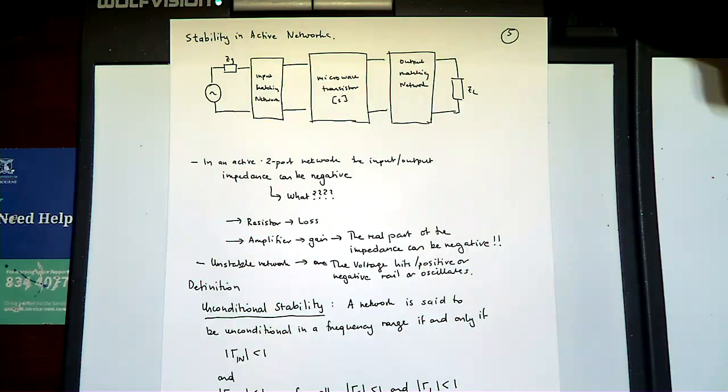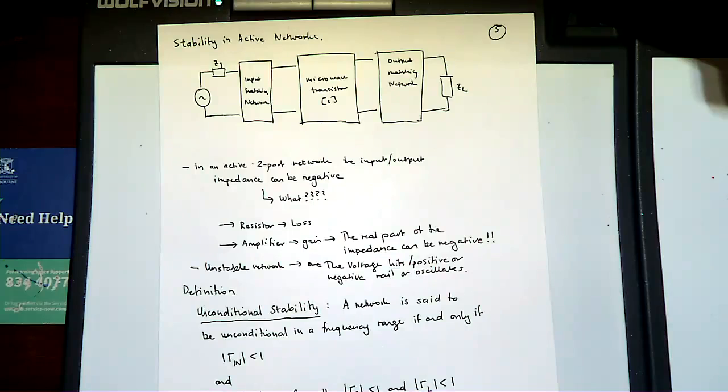That never happens in practice. In a real amplifier, you're going to hit the positive supply rail and it's going to stop. You're going to hit the negative supply rail and it's going to stop. It'll click. Right? Anyway, just a little bit of information. Okay, and from that note, let's talk tomorrow, and we'll talk about the concept of stability, unconditional stability, and tests for stability.